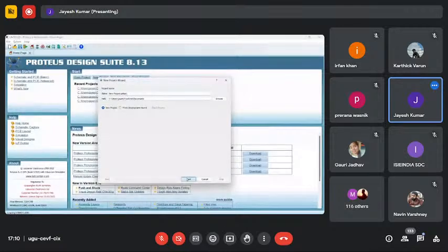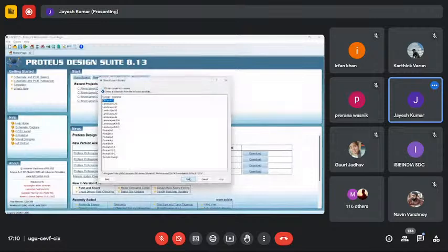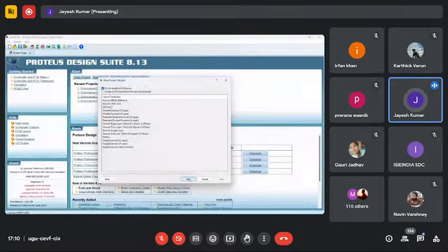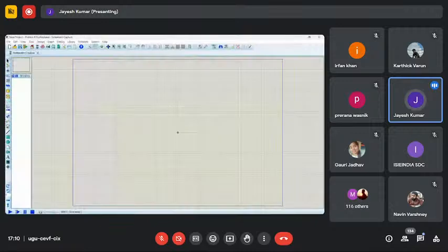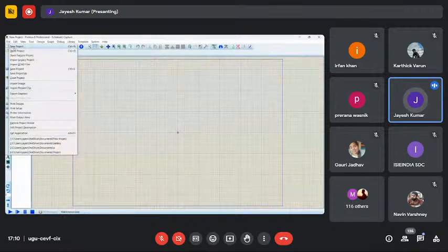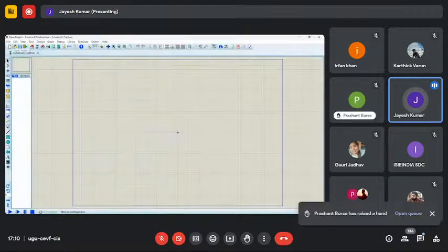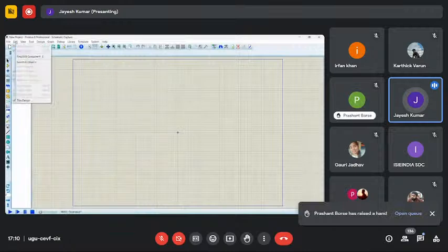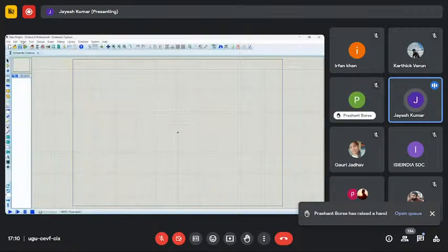First we have to save the component name, and then we just click it. Now I will show you the file menu, where you can import files. Here you can save your file or save as, or export to an Excel file, and you can also set up printing, to print the circuit directly from the Proteus software. The editing part is given here. In the view menu, you can change your dimensions and the cross-section parts of the circuits.